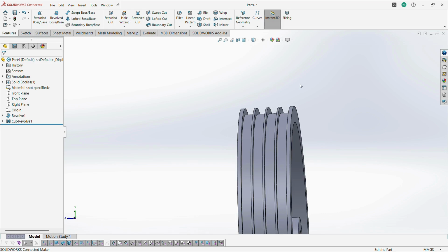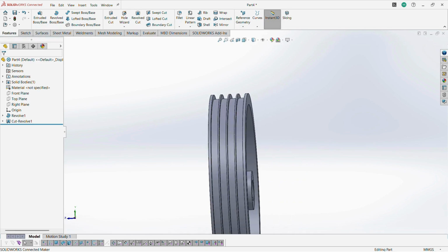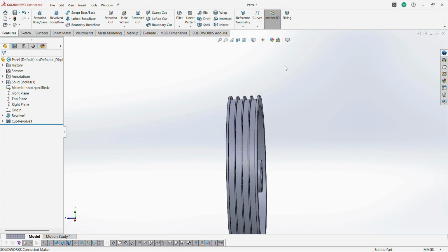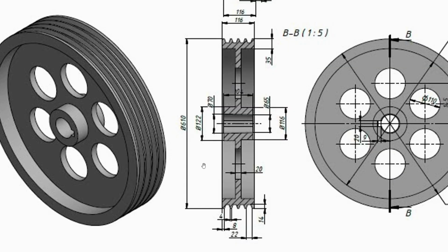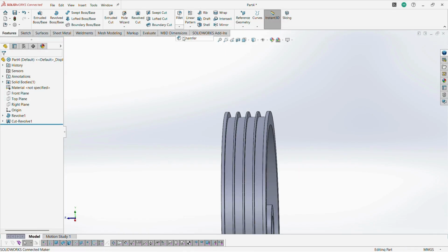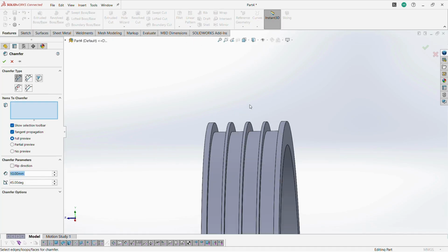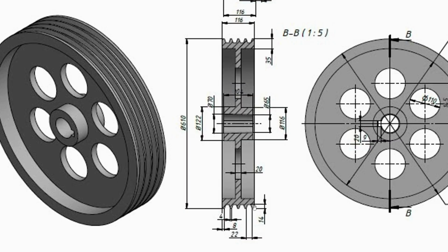If you take a look at the top portion, we need a teeth formation, but it is simply a revolve cut using rectangular profiles and chamfer profiles. We are going to use a chamfer to make an angular cut formation. Normally, if you select one of its particular areas, you can apply values. Now I am going to prefer 25 degrees and